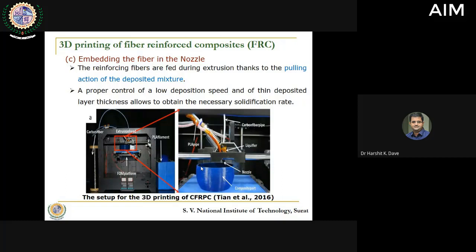There can be another machine which may work effectively from 170 to 185 degrees Celsius. So from machine to machine, certain trial has to be carried out initially to understand the temperature range through which this polymer, the selected specified polymer, is being printed effectively. It can pass the polymer, but once it gets deposited, it gets warped or the layers are separated. So if that happens, it means our strategy to print is not proper.